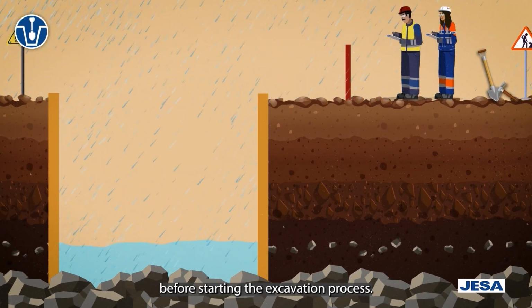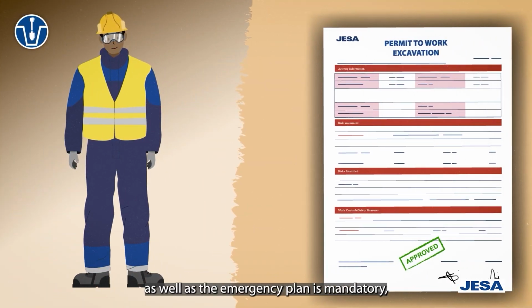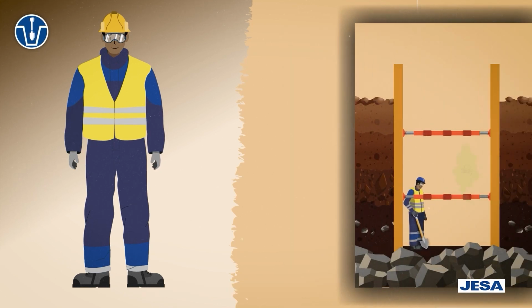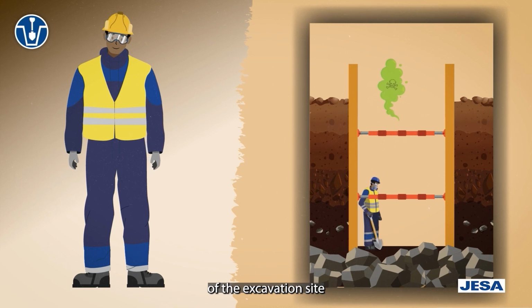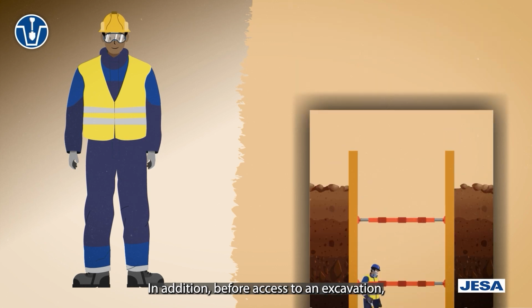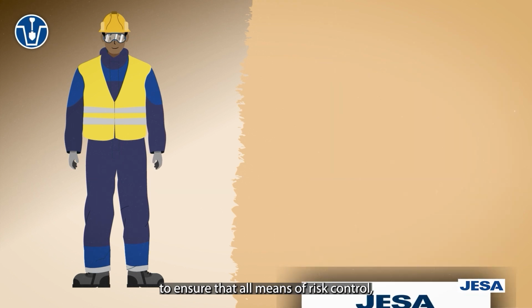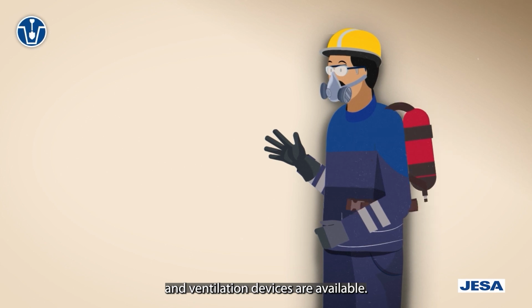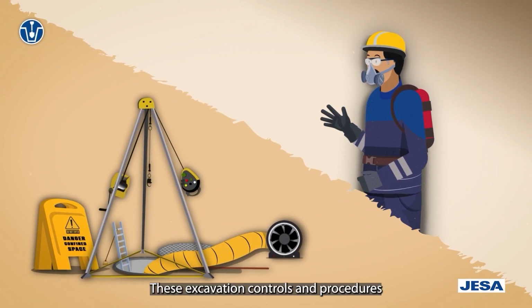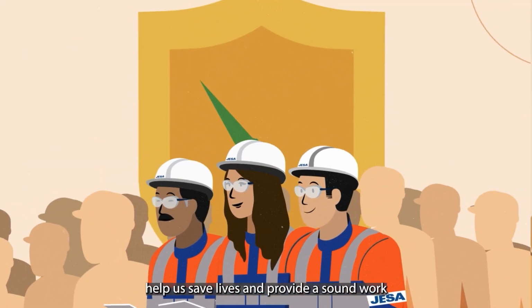Before starting the excavation process, obtaining the specific permit for the excavation as well as the emergency plan is mandatory, as you may face risks inherent to the activities of the excavation site or to the presence of toxic and flammable gases. In addition, before access to an excavation, it is imperative to ensure that all means of risk control, such as personal protective equipment, gas evacuation and ventilation devices, are available. These excavation controls and procedures help us save lives and provide a sound work environment.